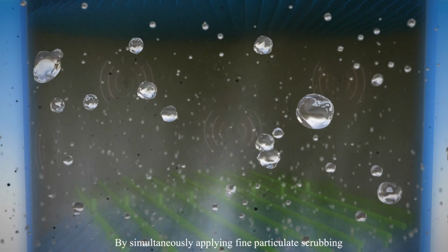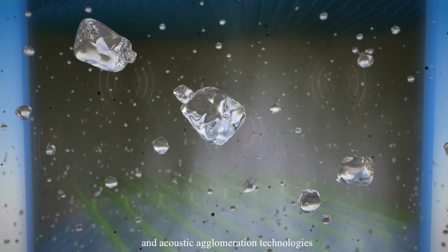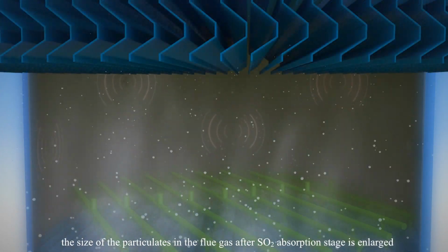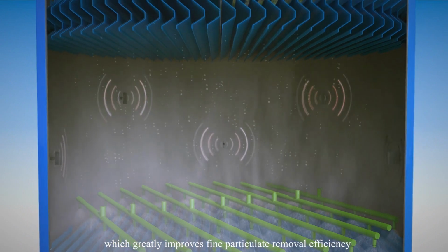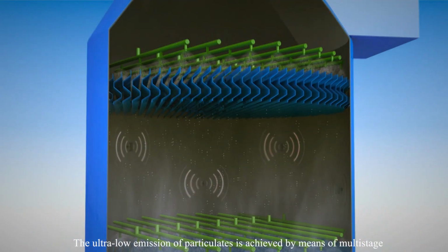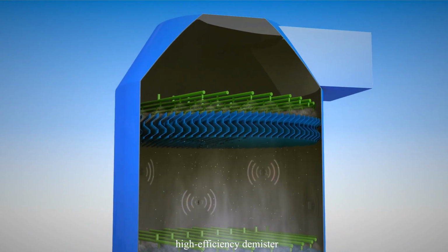By simultaneously applying fine particulate scrubbing and acoustic agglomeration technologies, the size of the particulates in the flue gas after the sulfur dioxide absorption stage is enlarged, which greatly improves the fine particulate removal efficiency. The ultra-low emission of particulates is achieved by means of a multi-stage, high-efficiency demister.